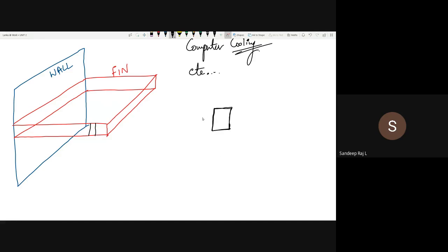See, when the heat transfer is happening through the solid, it is heat transfer by conduction. Within the solid, it is heat transfer by conduction. So Q conduction is entering here; let me call it at x. On the other side, it is leaving. This will also be Q conduction, represented at x plus dx, like we have done for our conduction case in the first unit. So this is Q conduction at x, and this is Q conduction at x plus dx that is going out.